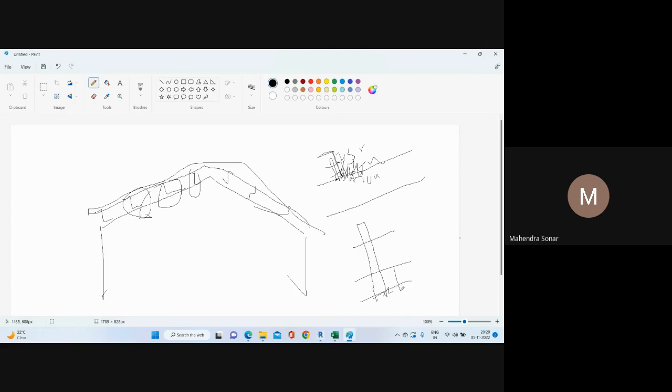So this is your 45, because we have added the 10 here, and this is 70, and this is 35. So almost 145 is the height of this plate. Okay, if you use this 10 bolt, your edge distance should be 1.5 times your bolt diameter. On the basis of that you need to calculate this.